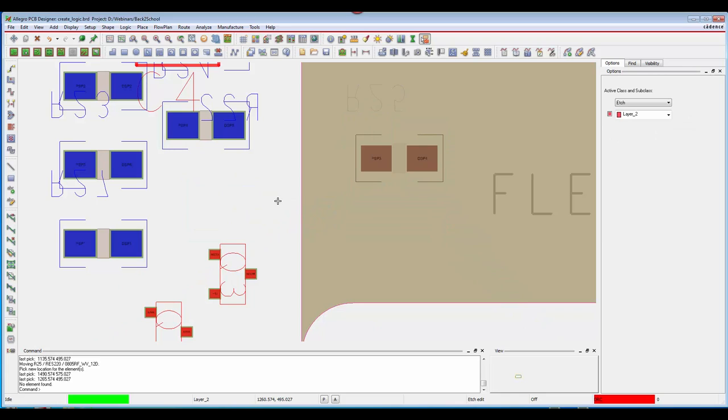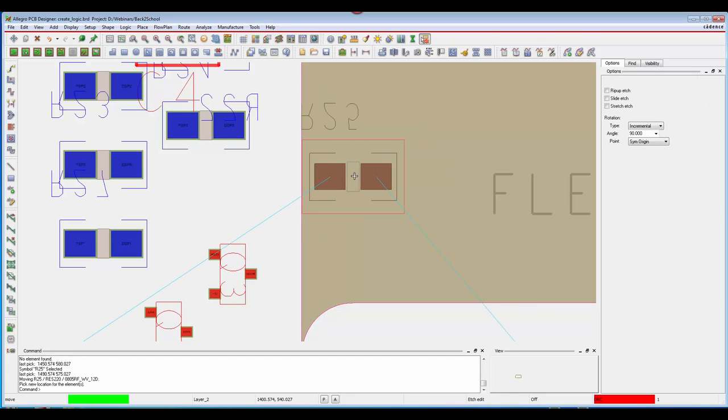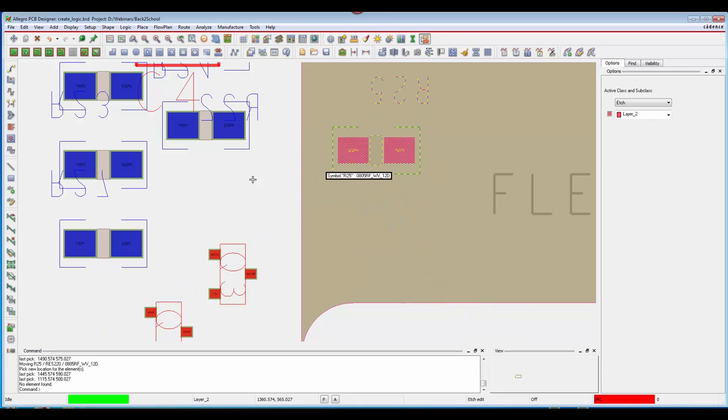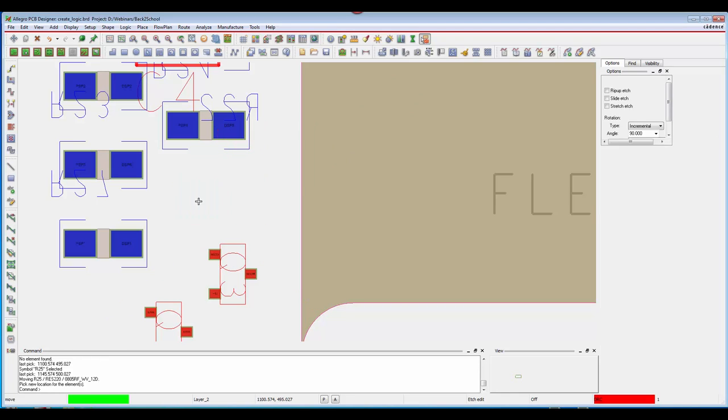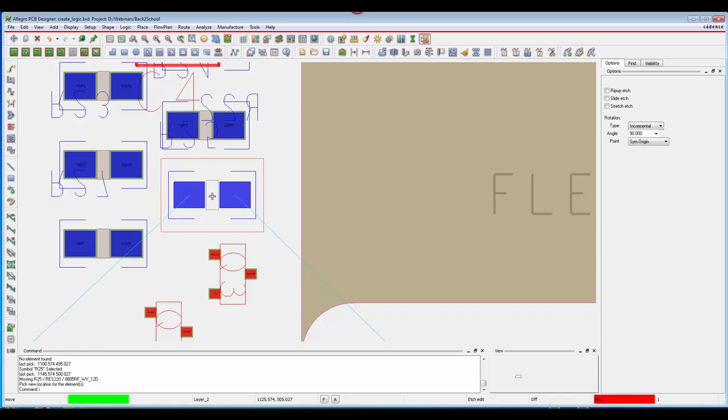As I move this across again, I'll now do some other component manipulation, such as mirror it to the top of the flex, and I can see it's gone to that particular top layer. Move it back to my 6th layer, and I can see the lead color change for that, indicating that this component is truly being pushed to the particular stack-up zone regions.